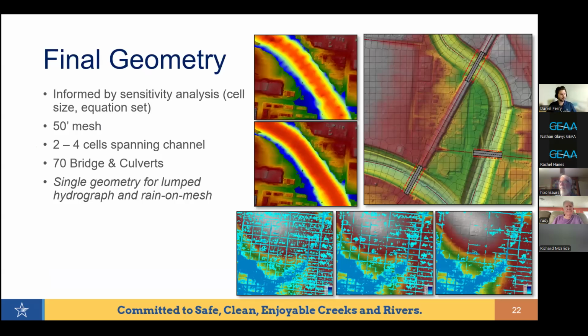So just to give you all a little bit of perspective on the model itself, we built the model to see how the water moves across the urban area. The model shows how the water moves in 2 directions, across and along the ground. So 1D, we're going from upstream to downstream, and 2D, we're trying to see how it spreads, basically. It has better calculations to see how it spreads, especially in flat and urban areas.